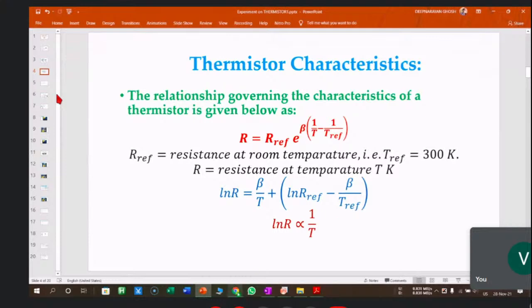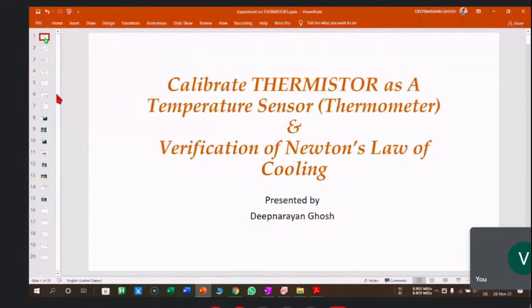Wonderful stuff, this thermistor. If 10 friends buy a mercury in glass thermometer, which is about 500 rupees, with that they can calibrate each one of them a thermistor, which can serve the purpose of a good thermometer at home. It is wonderful. First you need one thermometer to calibrate in a very good fashion, but once that is done, the thermistor is wonderful.